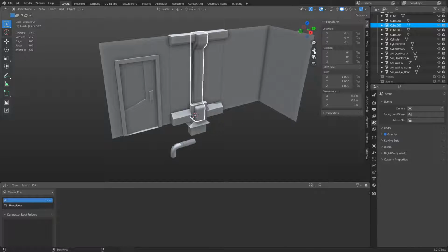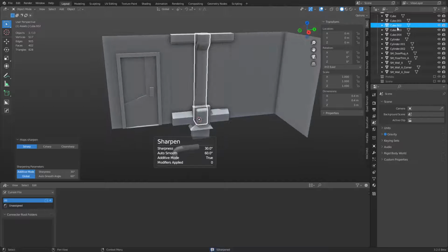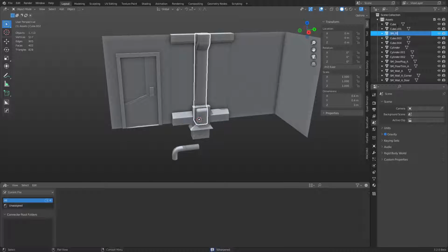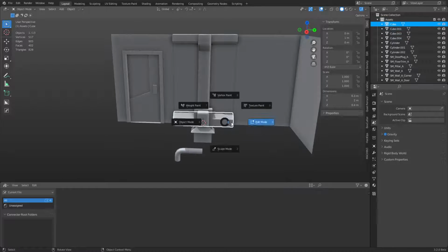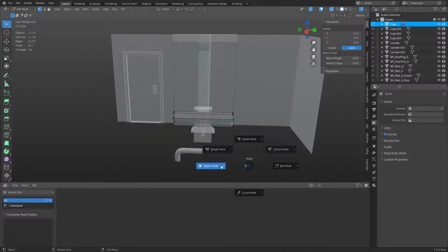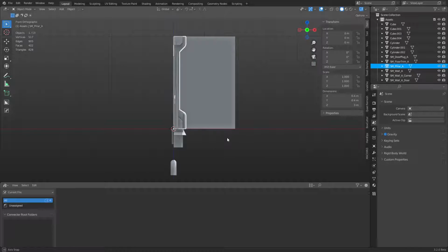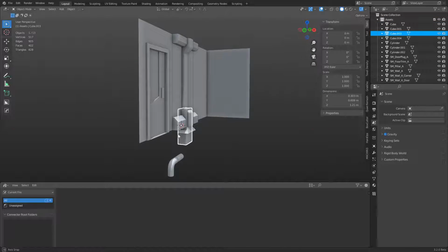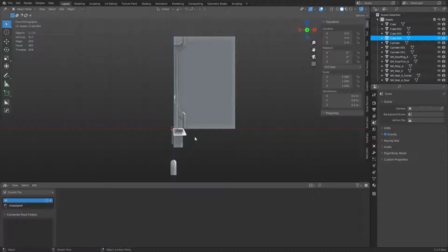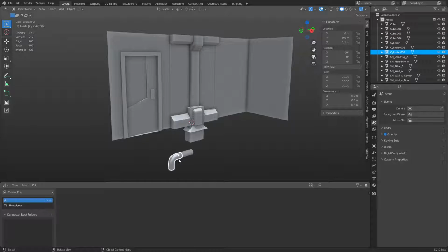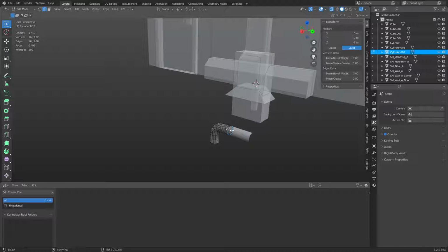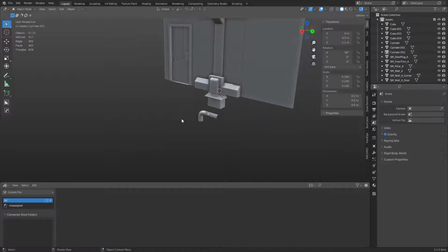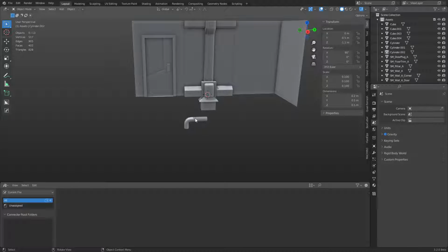And let's see, this is going to be sharpened. Oh, it is sharpened. Never mind. This is going to be static mesh pillar A. This actually needs the origin point up here. This one gets the origin point down there. Already is. Okay. So we got to start lining up all of our pivot points. This one's fine. This one is technically fine. That's fine. This one is not fine. I'm going to place it right here. All right, so now I got that. Might want to create a bracket system or some kind of mounting system for the pipes as well.